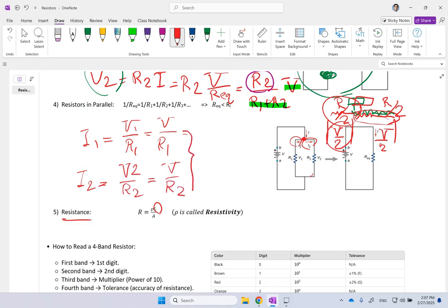And from these two, if you see that their numerators are the same, but denominators are not. So you can see that I1 over I2 is R2 over R1. In other words, the branch that has smaller resistance is going to take the bigger current, right? Between these two branches, which one of them will attract more current to it? The one that has a smaller resistance.